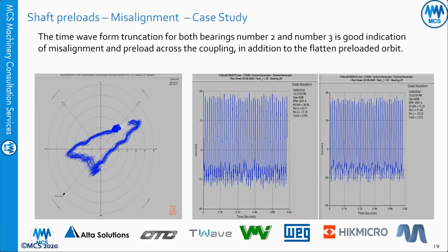All of this can cause rubbing, and the rubbing will increase the vibration and the temperature. So the most common things are the misalignment or the preload and the unbalance. These are very related to the load or the power, and the secondary damage related to them, like the rubbing, can happen as a result of unbalance or misalignment, and this will also increase the vibration.